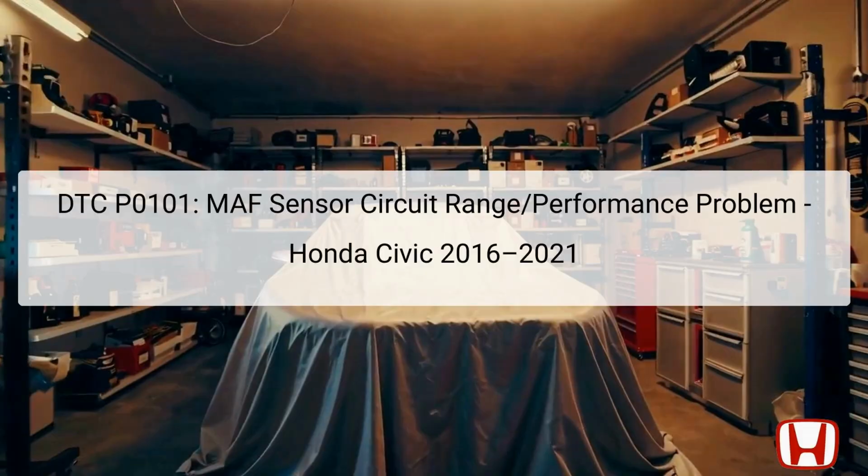DTC P0101 refers to a performance problem in the mass airflow MAF sensor circuit, indicating that the sensor's reported values are out of an expected range. The MAF sensor plays a crucial role in measuring the volume and density of air entering the engine, allowing the Engine Control Unit, ECU, to calculate the correct fuel-to-air ratio. This is critical for optimal engine performance and emissions control.